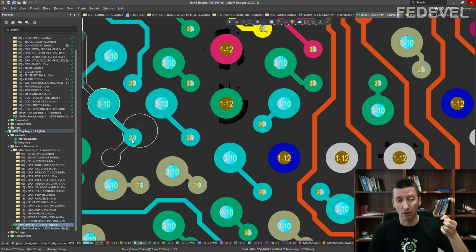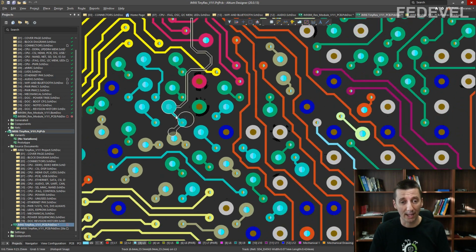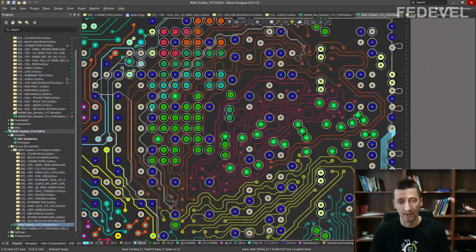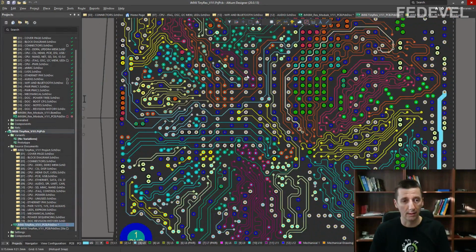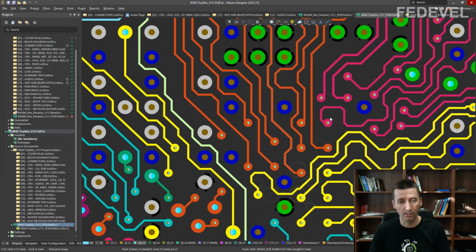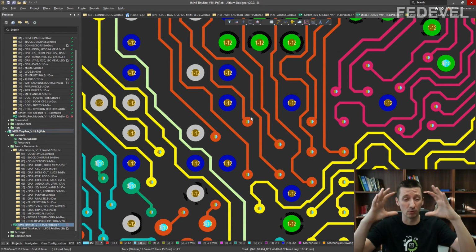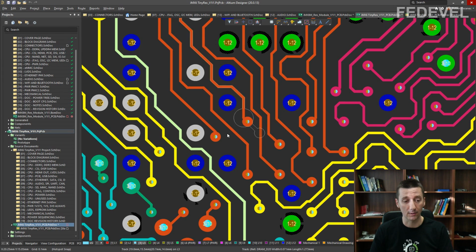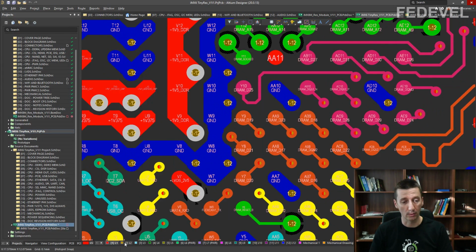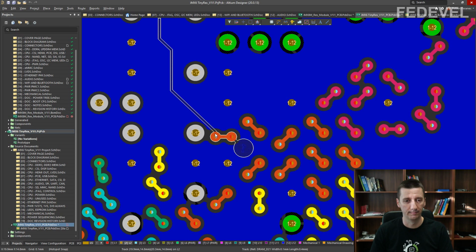And if we have to use a bigger hole, then I don't really need this small microvia here, because what I really need is the space on this layer 3, which I can save when I'm using these microvias. I will get a lot of space when I use microvias on layer 3. I don't want to use big, huge microvias. And that's the reason why I go from layer 1 to layer 2, and then from layer 2 to layer 3, because then I can use small microvias.